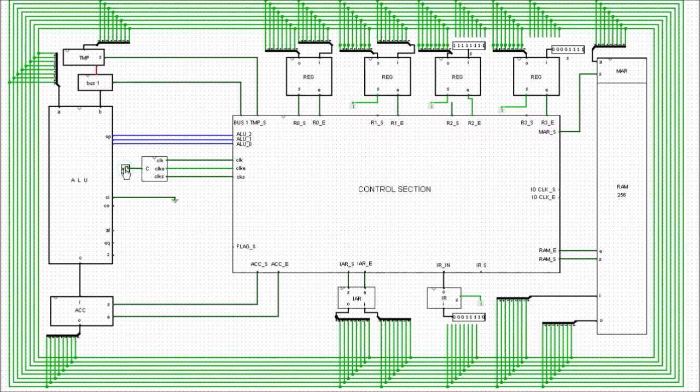In the next clock pulse round, we're going to grab all our 1s from this register here and stick them into that address we've just pointed to. At the next clock pulse, you can see the RAM has been set. So we've taken this information, which is all the 1s, and put it into the address we pointed to in the RAM.